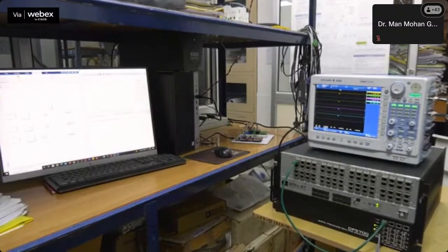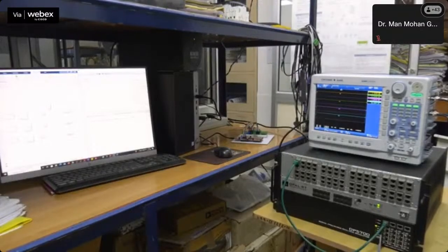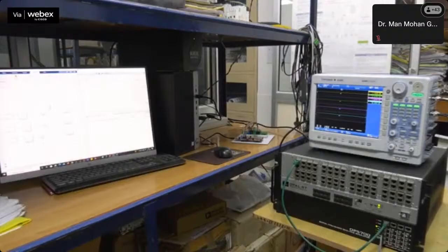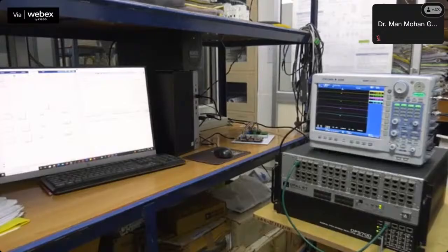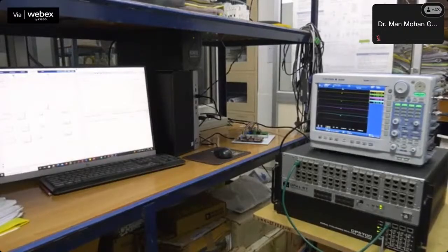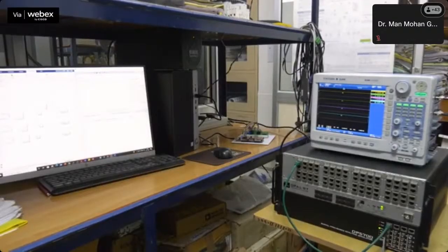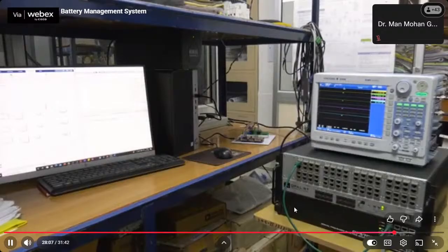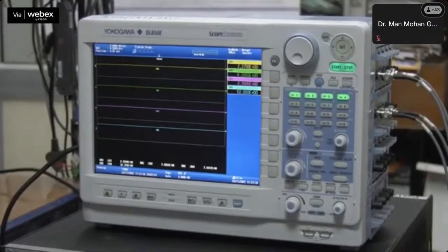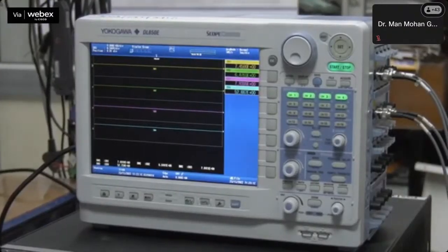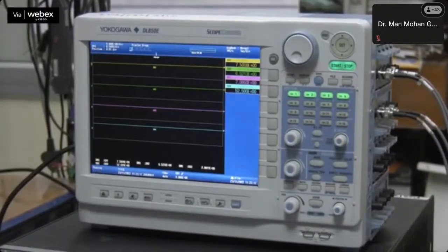Now, let us focus on the variations in load demand. To examine the control algorithm for load power variation, load power changes are applied to the batteries during discharging operation. Initially, the power demand is kept at 1000 watt and a gradual increase of power by 200 watt is applied till the power demand reaches 2000 watt.